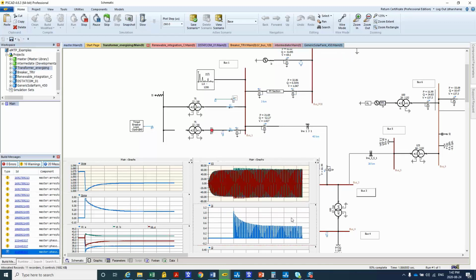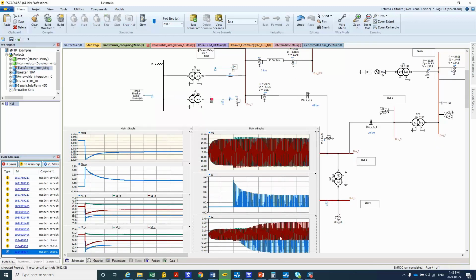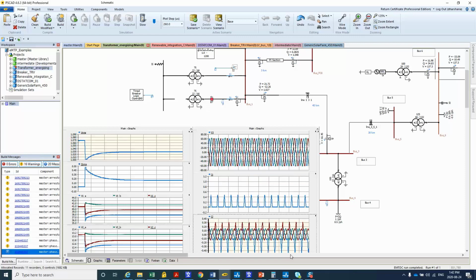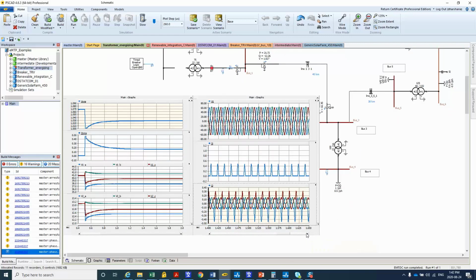And if you look at the results here, you can see that the inrush has not decayed as fast as in the previous case, and the transformer that was previously successfully energized is experiencing what we call a sympathetic inrush situation. See? So these are nonlinear events. Obviously, you need to study these in an EMT type environment.